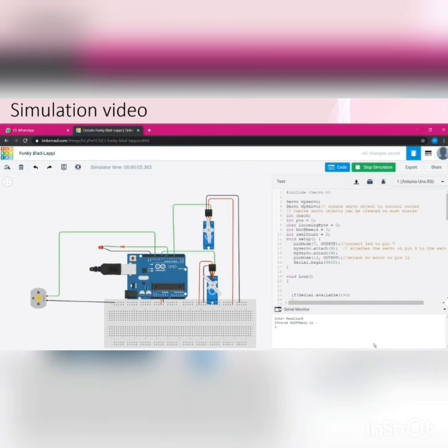Since this process should be continuous and work for a certain amount of time, the code of the DC motor and servo motor was written in the void loop, which helps keep the process going for a certain amount of time. As soon as the winding is done, servo motor 2 turns on for cutting the silk thread.